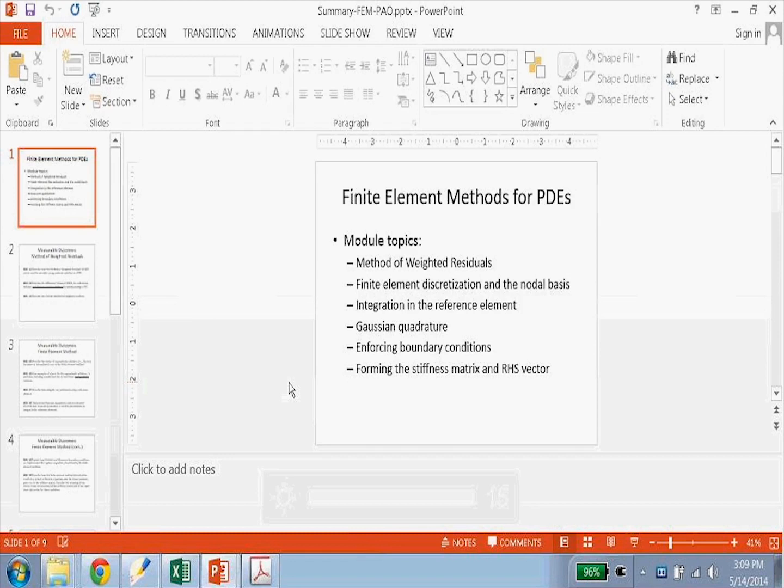We want to write down then the jth weighted residual. We'll call it R_j. And what is it? Take everything over to the left-hand side, substitute in the approximate solution. So we get k dT tilde/dx, all differentiated, plus q. Weight it with the jth basis function, and because it's Galerkin, we use the same phi, so we weight it with phi_j, and then integrate over the domain, from minus L over 2 to L over 2. I can write out all the steps, but you've seen it many times in the notes. So we get that, then what's the next thing we do?